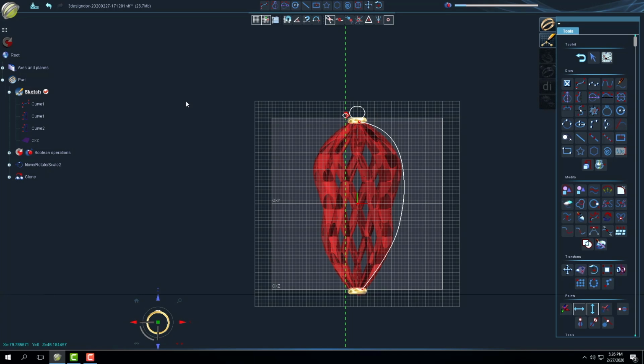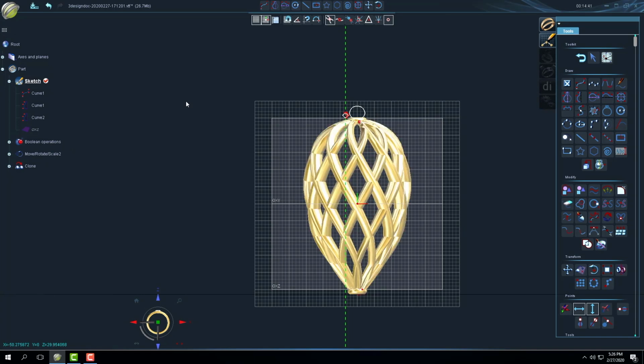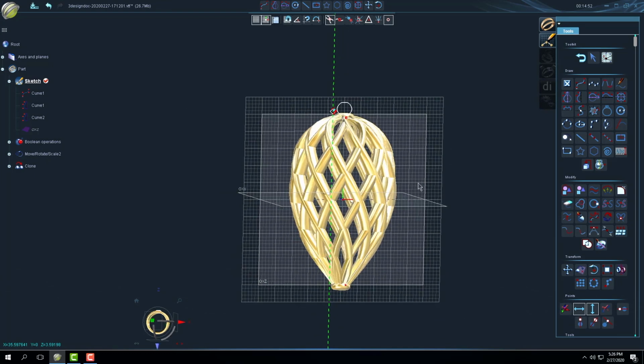You can also check it with something called polygon conversion, where it shows a mesh, and you can see in the mesh where they'll be highlighted in red if there's an issue, and if there is, then you can go back into the model, make adjustments so you don't have shared surfaces and so on, and then relaunch it again. So even before you save it or export it, there are lots of ways to check it and make sure.